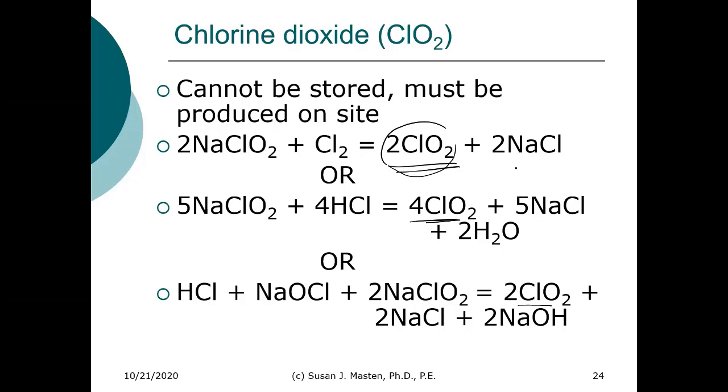So you can see by this reaction also, we're going to increase TDS because we have NaCl. Same thing here. And in this reaction here, we're going to produce a sodium hydroxide. So we will both increase TDS and we will increase the pH.